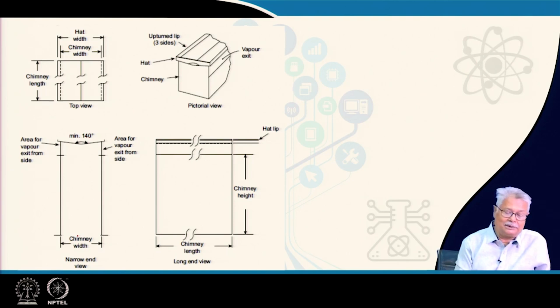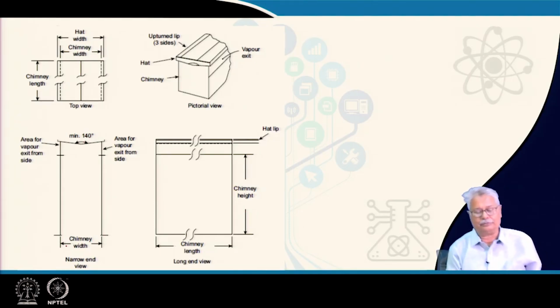The top in this particular case is not convex, it is not just a hat, it is an inverted hat. And what happens is, I have mentioned about the upturned edge of the hat. The upturned edge does one thing, it collects all the liquid on the hat and allows it to drain from one side only. So, quite naturally what you have is it will be collecting all the liquid here, and from the thinner, the less wider end, it will be draining off.